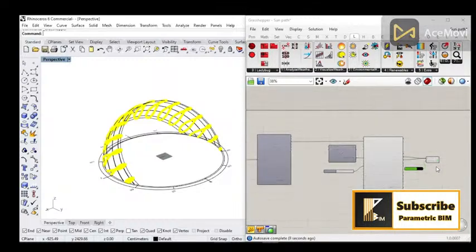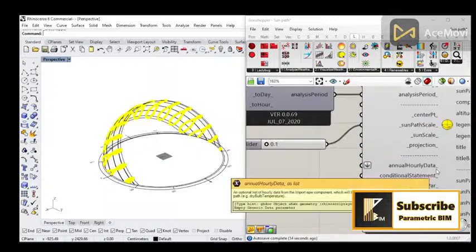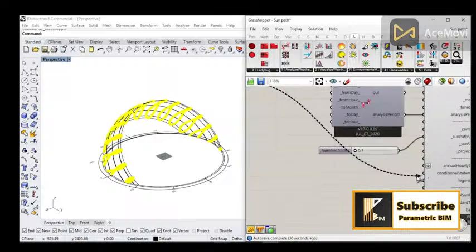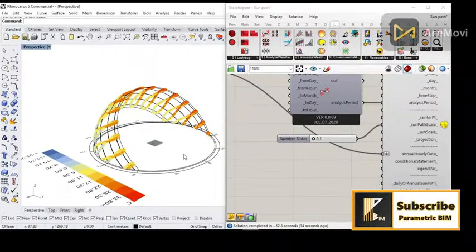The final thing that I have to show you is that we have here annual hourly data, and we can connect any data from the EPW file to this input and it will work. This means that I can make the sunpath based on dry bulb temperature all over the year, for example. So if I connect this to annual hourly data, you can see that the sun will be colored according to the temperature all over the year. And yes, we are done now.